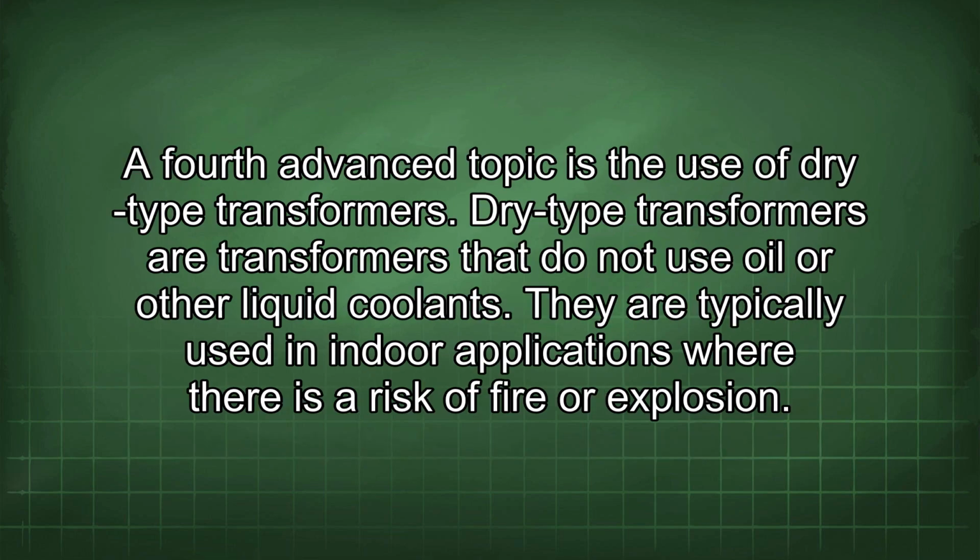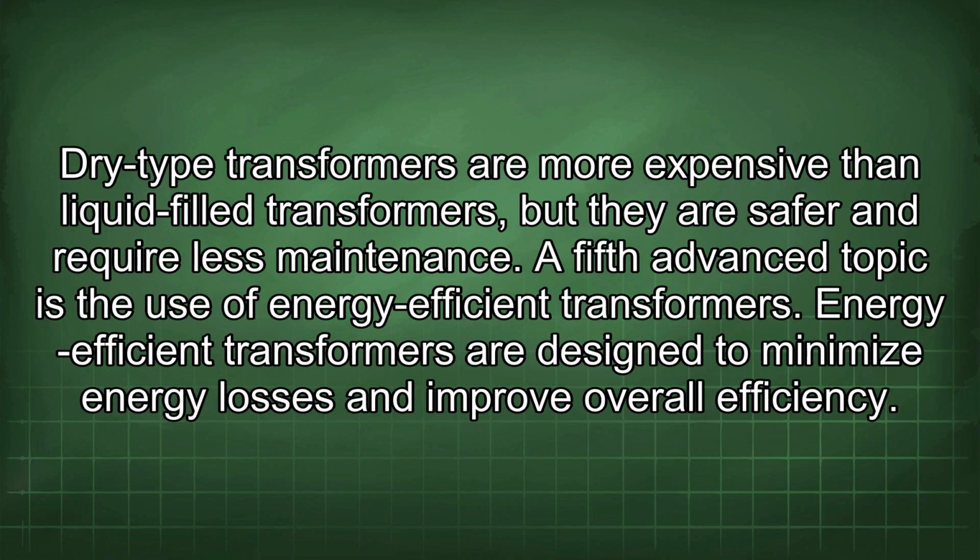A fourth advanced topic is the use of dry-type transformers. Dry-type transformers are transformers that do not use oil or other liquid coolants. They are typically used in indoor applications where there is a risk of fire or explosion. Dry-type transformers are more expensive than liquid-filled transformers, but they are safer and require less maintenance.